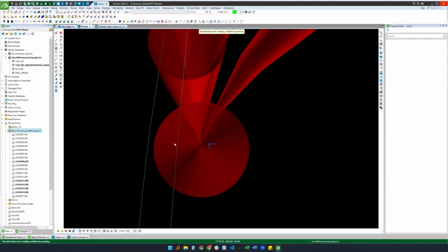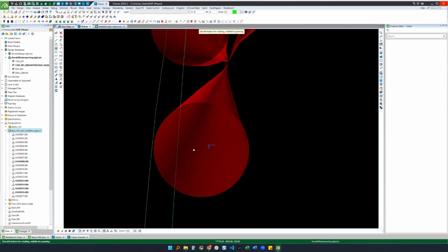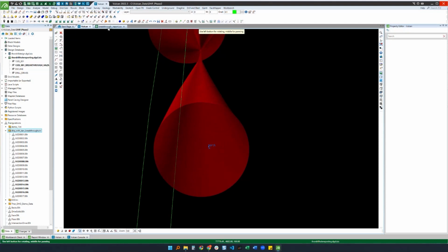So that's what we're getting here: the distance between the closest point on this section of hazard object inside the cone to the actual drill hole trace itself. So that's the one that's really important. You want to see how close it's getting to your trace.